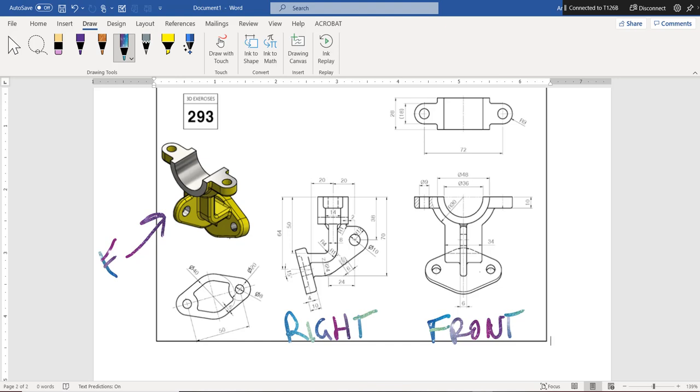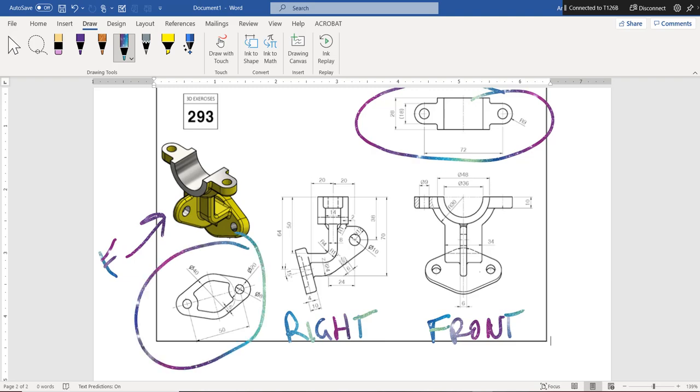And this technically shouldn't exist because this view right here is technically incorrect unless there's a sectional somewhere on this drawing allowing us to do that. This view should have a sectional reference because this is what's called an auxiliary view. Okay? And this technically is the top of the part, but it's in the wrong place if you look at it.